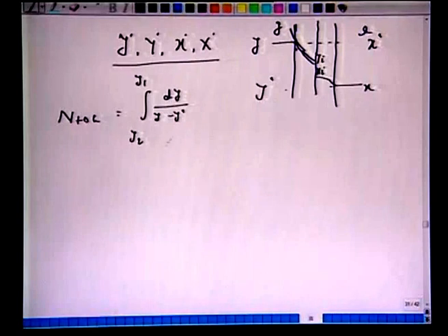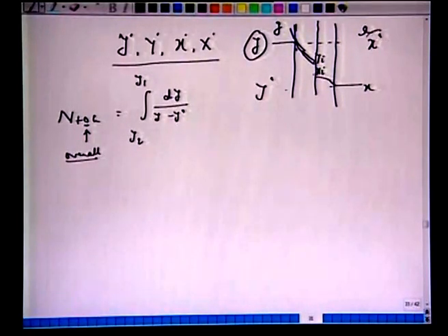So, notice here now we are using NTOG, where O means overall. That means we have avoided working on yi interfacial concentrations, and instead we work on x star and y star. So, x star would be the equilibrium concentration as if the entire bulk phase concentration is brought to this interface in equilibrium with this bulk phase concentration. Similarly, we have y star for a given x.